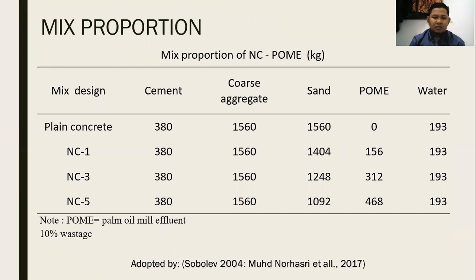This is my mix proportion. This mix proportion was adapted from Sobolev in 2004, who used it for normal concrete, and from there I made the mix proportion for my mix design. For every mix design, I included 10% of wastage.